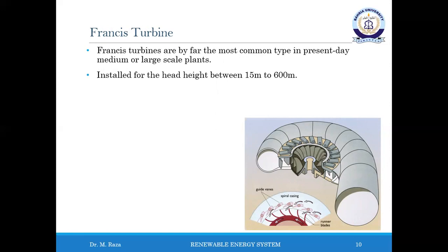The Francis turbine was originally designed as a low-head machine installed in an open chamber without a spiral casing. Although efficient, the Francis turbine was eventually superseded by the propeller turbine, which is more compact and has a faster runner for the same head and flow condition. However, since many open flume Francis turbines are still operated, this technology remains relevant for refurbishment schemes.